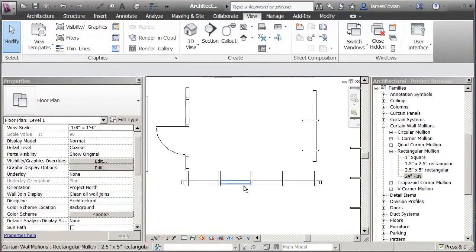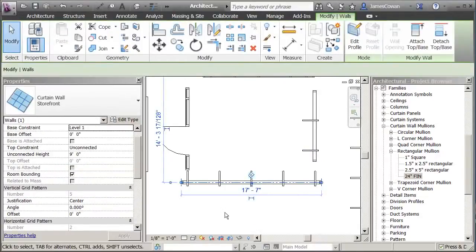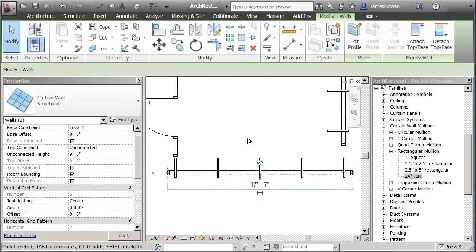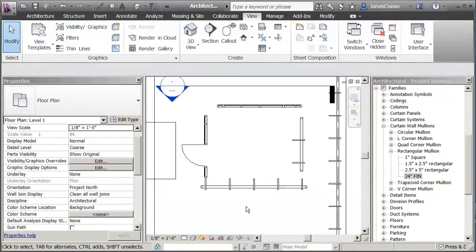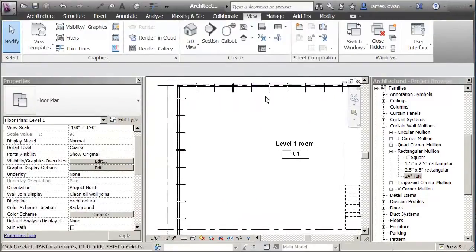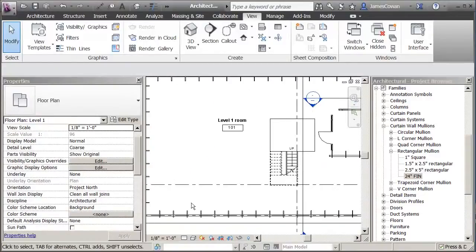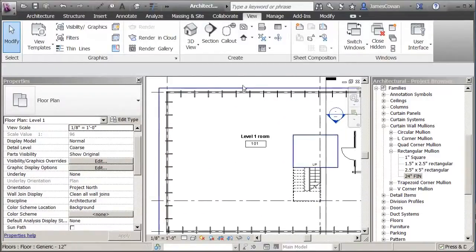You won't have a case where in some places the curtain walls are being moved in, and in other places they appear to be being moved out, because you don't have a flip symbol to flip it over. You can do it with the space bar, but you don't want to have to go around all the walls of your building that are using this setup. You want to be sure that each of them knows what is outside and what is inside.